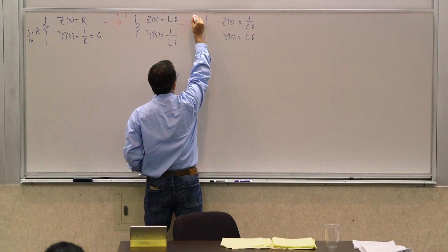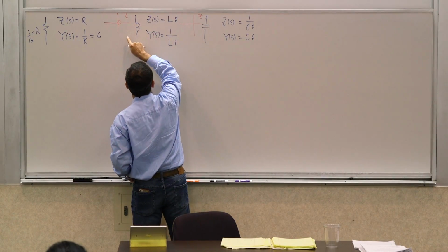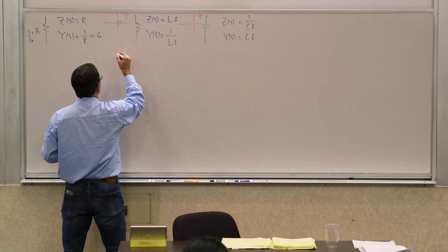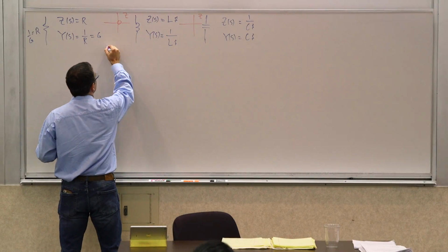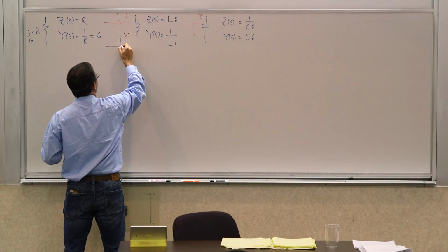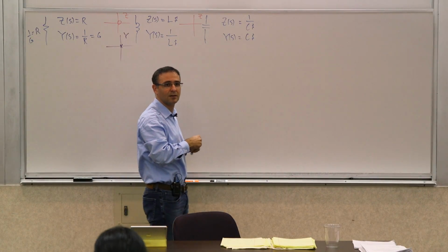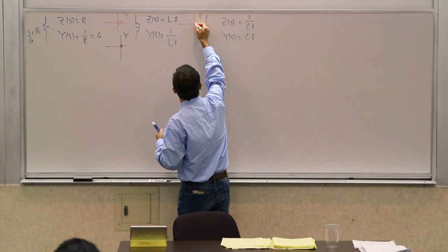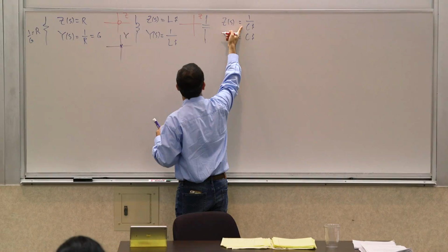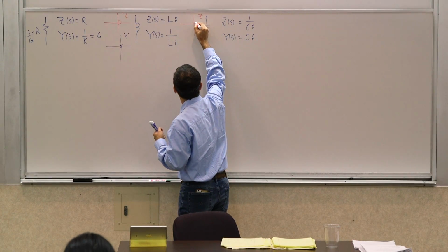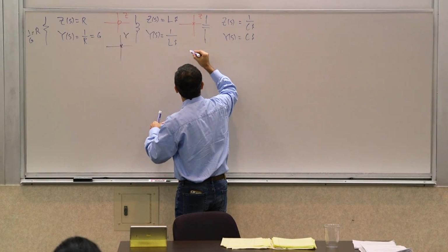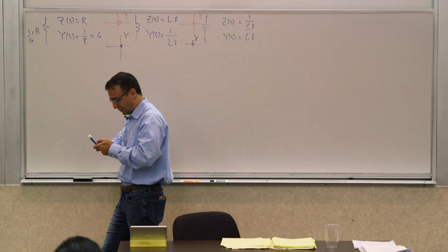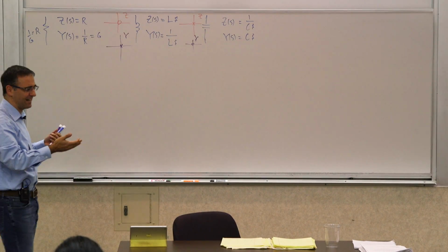Now, how about this one? If you look at the impedance, or I could also do admittance if you want. If I look at Y, then this is going to be a pole for Y, right? And now here, what do we have? For Z of S, the impedance, I have a single pole at the origin. And for Y, I have a single 0 at the origin. You can think about it that way. Okay, so that's, again, rather trivial.